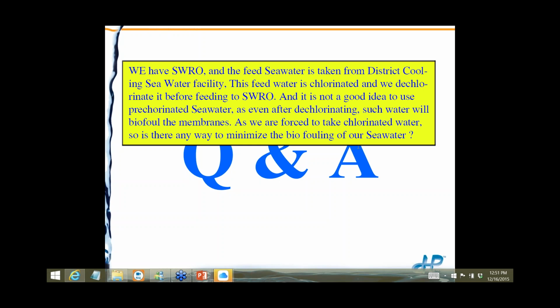That is a huge problem in the industry. I consider it overall the biggest problem with RO membrane water treatment, and that is chlorination, dechlorination. The active chlorination takes organic molecules that bacteria can't eat and turns them into molecules that they can eat, called assimilable organic carbon. So it's a huge problem,